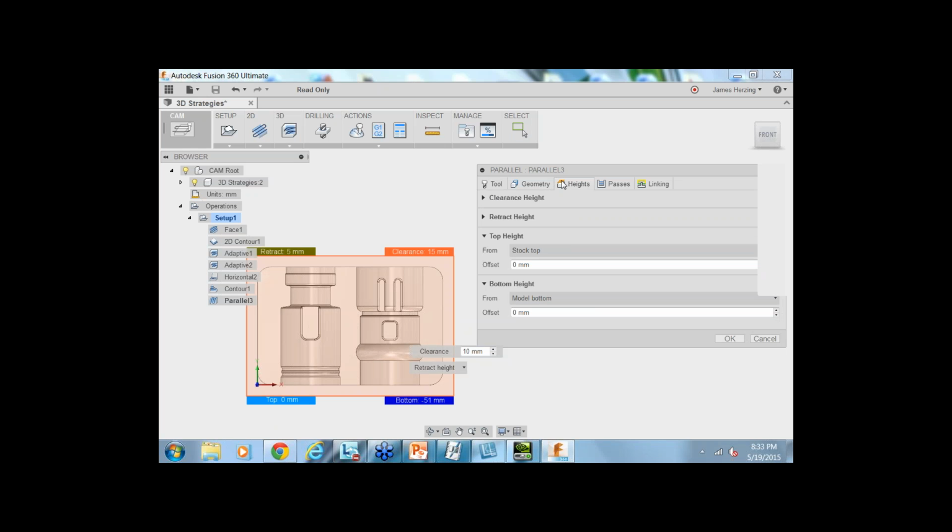One more time, I'm sorry. Remember that contour thing I gave you, that ridiculous thing that took 28 hours to machine? The way Alex cleaned it up was by taking those C-shaped regions from the contours map and projecting those up onto a plane, and then constraining the machining area to just within those projections. So I think it would be useful for other people if you cover that. Okay. And it's an option when you select constrain area, which is what you're covering. Constrain area.